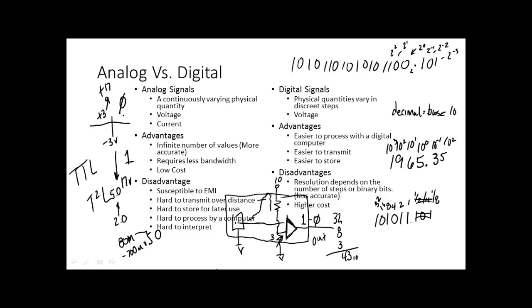They guaranteed it. The specification said 50 feet, but I saw this stuff. The higher the voltage level you have, the further you can send it. Standard was around 15 volts, because that way you could shift. So 15 volts, think how much that sucker could shift before it got below 0 volts, right? You understand that? Which was really neat. I've seen RS-232 run thousands of feet.